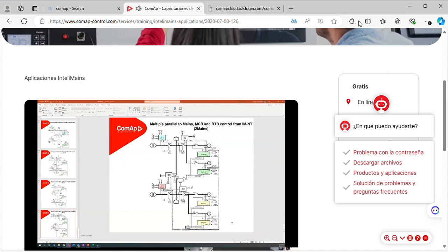So once I press close BTB, it will perform synchronization again between them. So it is synchronized and the bus tie breakers are closed. Now you will see the load is changing between them. Immediately the load on the third genset fell down and they are equally sharing the load between them. That's manual operation. But suppose I switch the entire operation to auto mode,